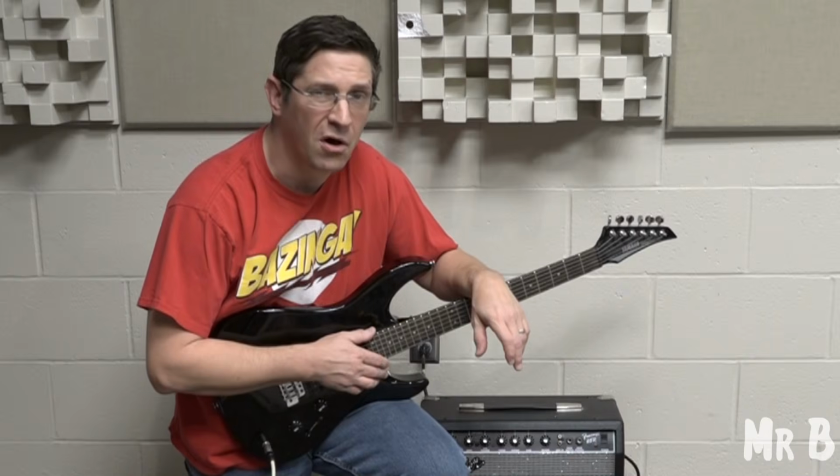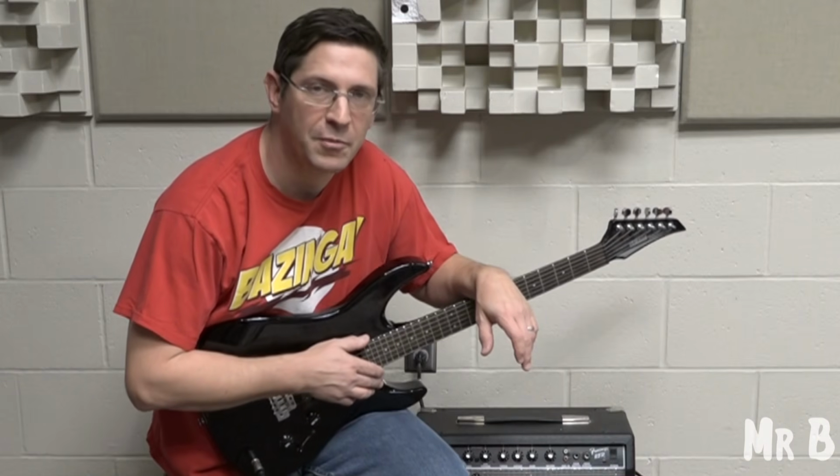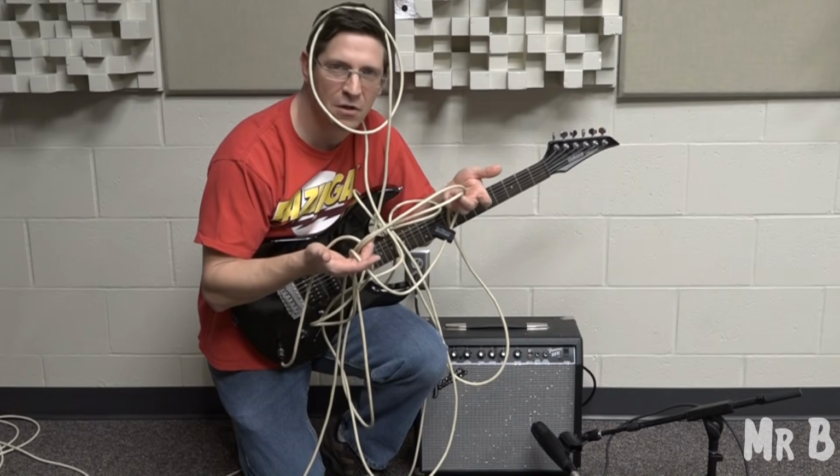So this happens with all cables? Yes, all cables have this issue. Then why doesn't this happen with microphones? Ah, good question. Well, remember that microphones have a very low output impedance. This allows us to have a much longer cable run before its internal capacitance causes us to have any audible high frequency loss. So, cut to the chase, how long is too long?